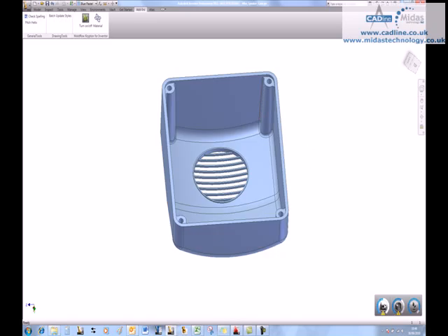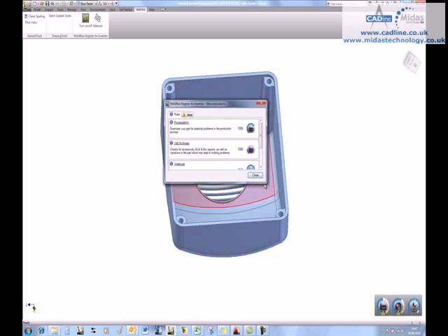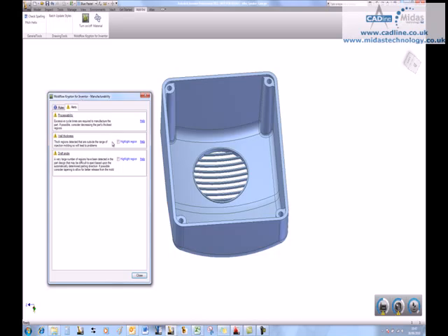Right, we come back down the bottom over here, and we'll now have a look at manufacturability. It has a little exclamation mark. Cost efficiency also has an exclamation mark, and material impact is right over on that scale, but it looks okay. So we click on these, and we have a look at the manufacturability and what's come up over here. It says processability examines the part for potential problems. It checks the wall thickness, checks for undercuts, and checks for draft angle. We're going to have a look at our alerts and processability. We have excessive cycle times, and that's because we have some really thick areas on the components. So the wall thickness is quite high and there's lots of material in here, so they're saying we're going to need excessive cycle time and possibly high clamping forces.